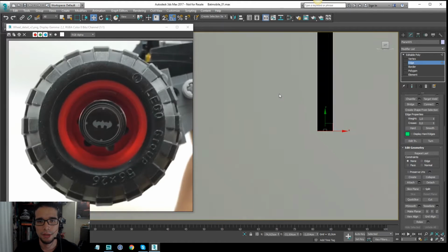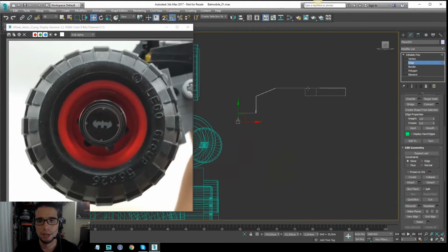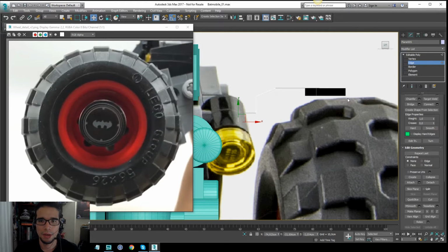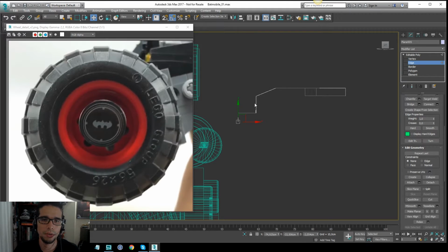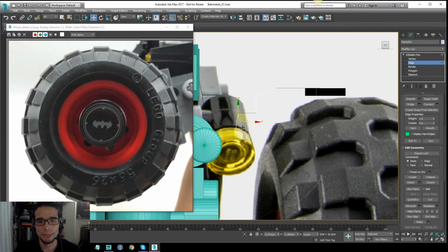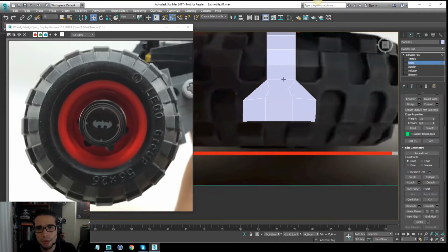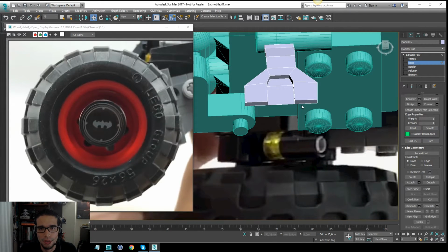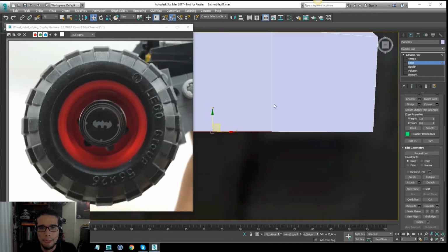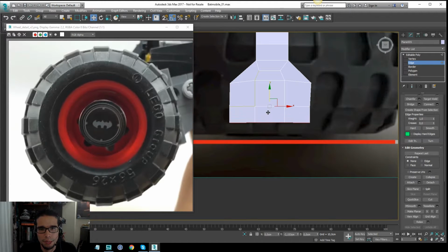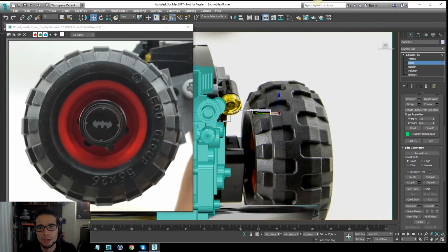If I verify in this particular view, like I said, it's not precise, but you see there is a flat surface, a diagonal surface, one step, a turn, and one step. It's something like I have here, a flat surface, diagonal down, something like this. Later I will adjust the position and things like that. So right now I have this part of the wheel. The other ones, for example, this vertex here, I will select them. Let me see, and I will extrude them again, and verify the shape.